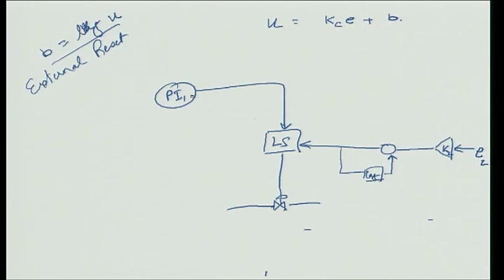Similarly, this PI controller can be seen as: you got the error in the first variable, you multiply it by a gain, and then add to it lag 1, and let us just call this lag 2.